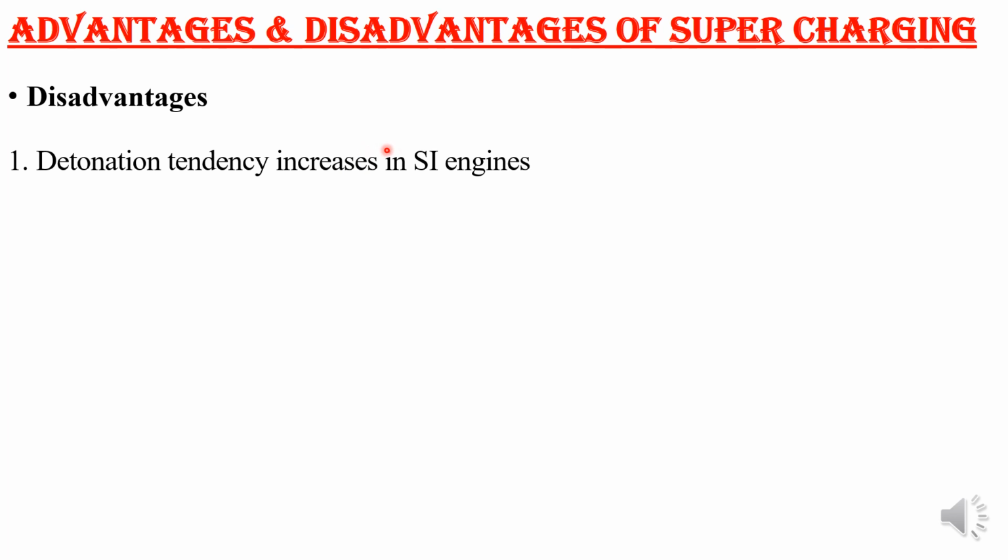So this is one of the disadvantages, so that more boost pressure cannot be used, up to 1.3 only you can use, so that power output can increase. Beyond that, it may lead to detonation. Once detonation is formed, that means the life of the engine is reduced. More damage in the materials can be obtained. So this is about the detonation problem while using supercharging.